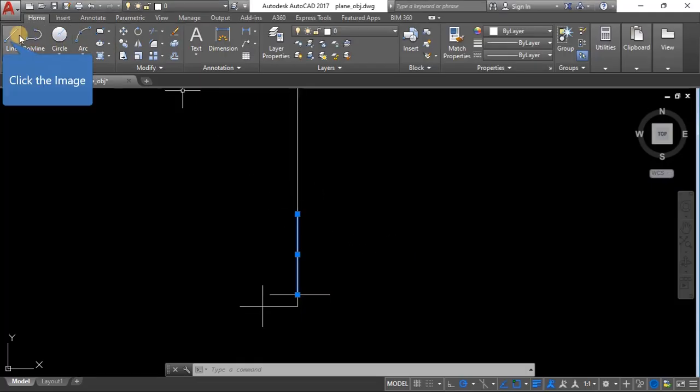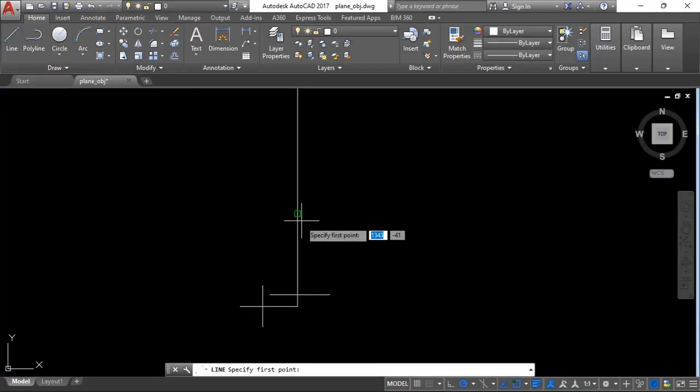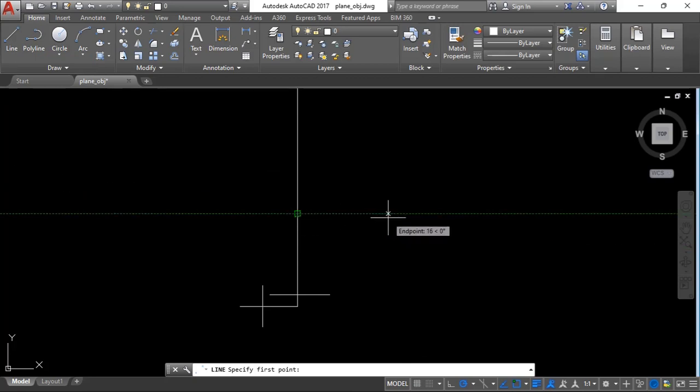From there I'll just look for that end point. You actually don't need the line per se. You can just start it off at a distance of 42 from that end point. So 42, press enter. That is my point.